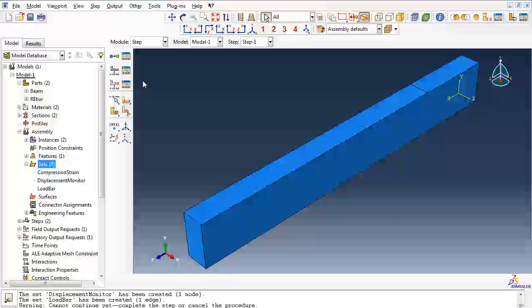So we are only interested in the ODB and the .dat output types of the 4 available in Abaqus for this analysis. The output database, or the .odb file, is for visualizing purposes, and it's also used by Abaqus for post-processing. And the other output types are printed tables of results. They're written to a .dat file, and we'll use these results from tables and import them to Excel to plot the results and compare them to our actual experimental results.